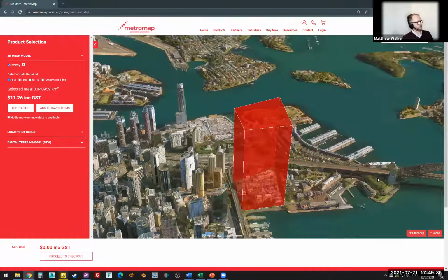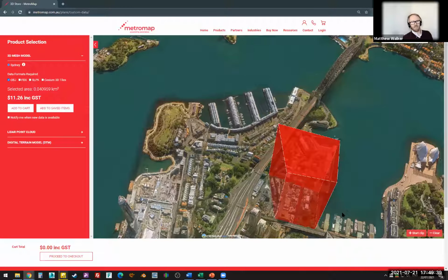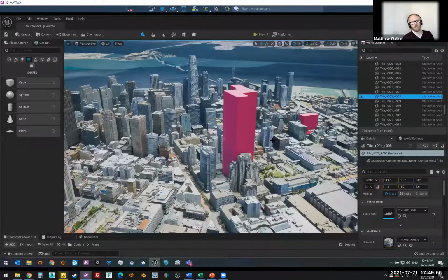Revit is actually a tricky package. It doesn't like a lot of mesh. It uses procedural geometry, and it has moved away from some of those raw triangles, which is exactly what our data is based on. So there are ways to combine them together. Sometimes you need to push it back out to Navisworks as a way to merge those two data sets together. Sometimes you push it out to programs like Twinmotion or Lumion. But certainly, using the data for different stages, initially for design, maybe for approvals and consultation, but taking it through to construction planning, it can be used for construction sequencing to great effect as well.